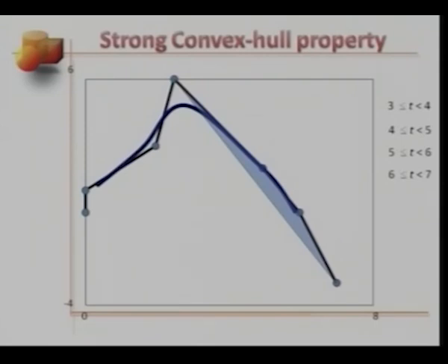Now, if you notice, the values of t are in the knot span corresponding to the full support. It's for these values of t where we have all 4 B-spline basis functions non-zero for any t. Now, if you look at the overall convex hull or the parent convex hull defined by all the design points, it looks like this.